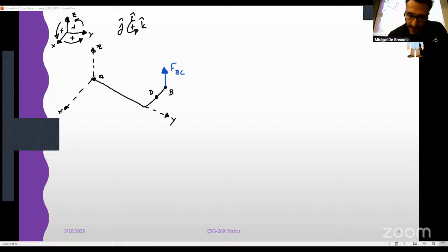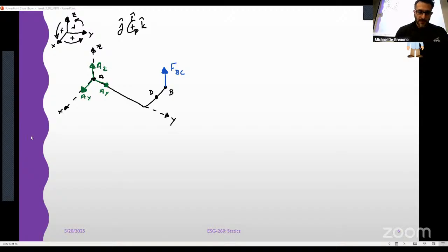So in this case, we'll start with the forces, right? I've got this guy, AX, this guy, AY, and this guy, AZ. Maybe that wasn't the best color, but okay, great. And we have rotation. Now, a thrust bearing clearly does not allow us, it keeps us in place. It's going to allow our shaft, our rod to spin, right?